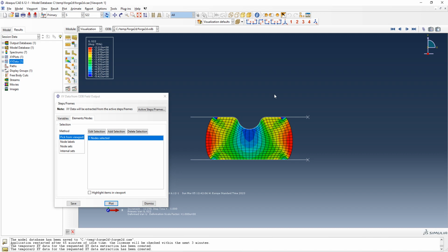So this will be kind of a multi-step forging process with some post-processing and looking at how the stresses or strains are distributed, and how we can post-process the data from the simulations. And then of course you can go crazy, you can apply all kinds of boundary conditions, you can change your material model, you can change the shape of the die, and you can try it for yourself how the simulation model is working. So let's do that.